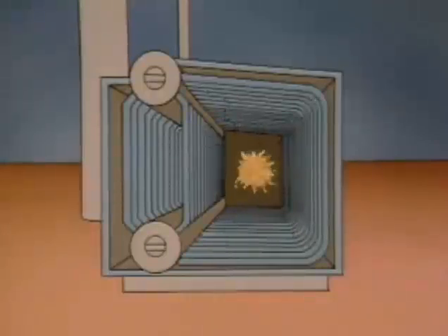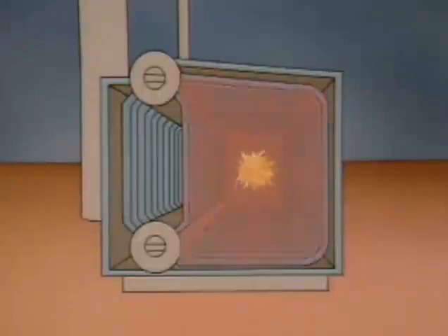The burning fuel also produces combustion gases. As these hot gases pass through the boiler, they transfer heat to the tubes as well. This is convection heat transfer. As the outer surfaces of the tubes absorb heat, conduction heat transfer occurs. Heat is transferred from the outer surface to the cooler inner surface. Then heat is transferred from the inner surface to the water flowing through the tube. Convection heat transfer also occurs as the warmer water mixes with cooler water. When enough heat has been transferred to raise the water temperature to the boiling point, steam is produced.